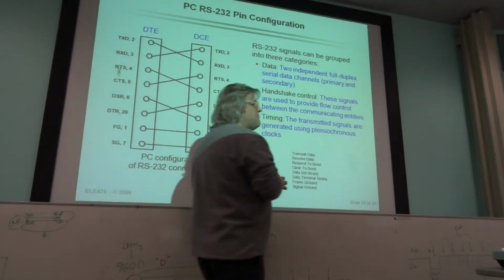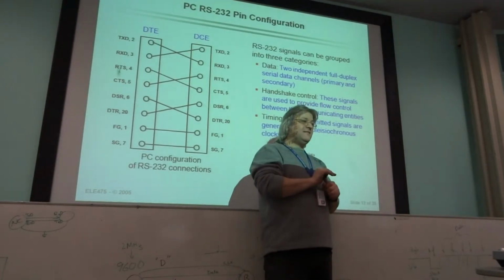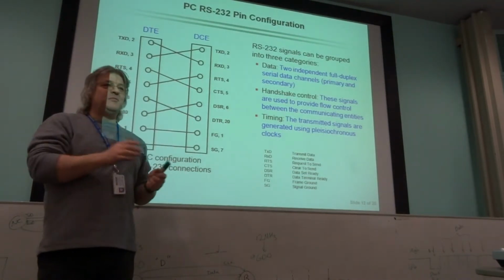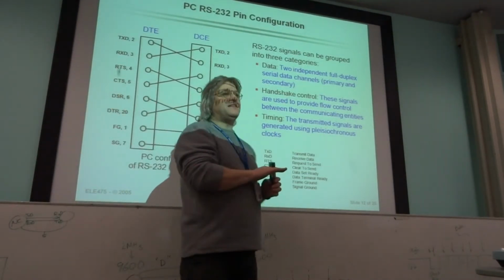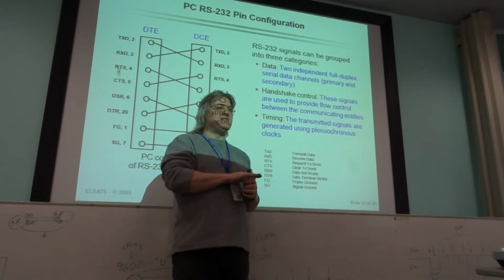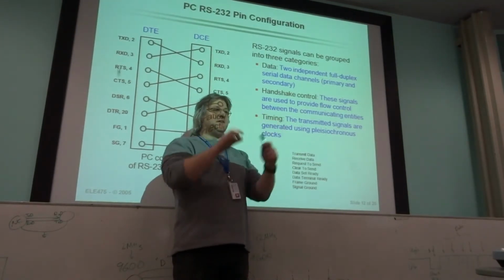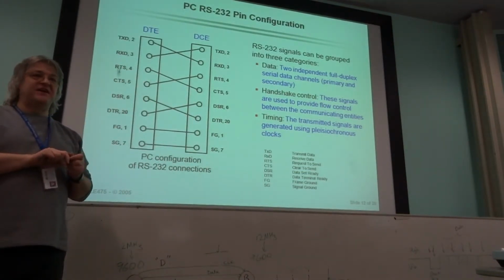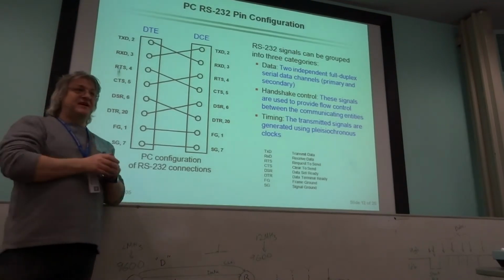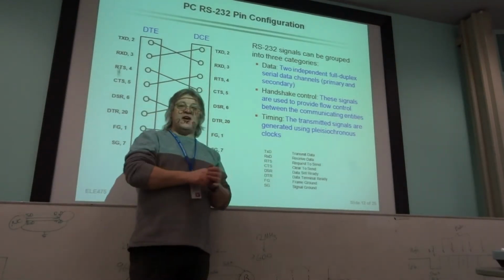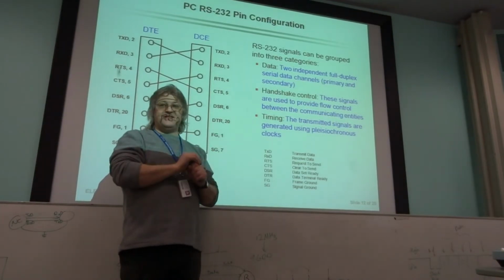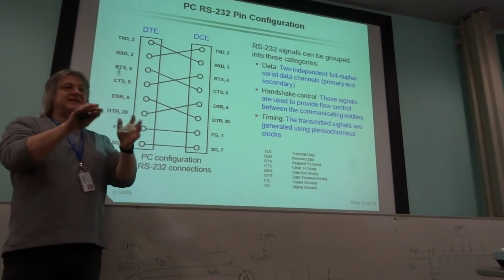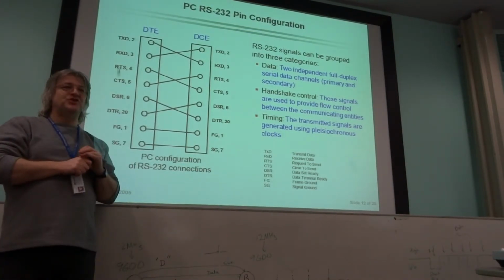An example of this might be if you're using a PC, which is not true of all modern PCs, but certainly PCs as of a couple of years ago, most of them had RS-232 compliant serial interfaces, which was a little D connector at the back of it. By default, they would normally use handshaking. So you could use that connector to connect to your 8051 system, and you won't see anything happening because unless you send the clear to send, nothing's ever going to be sent to you. The solution is on the PC, you would tell it to configure its serial interface to use no handshaking.